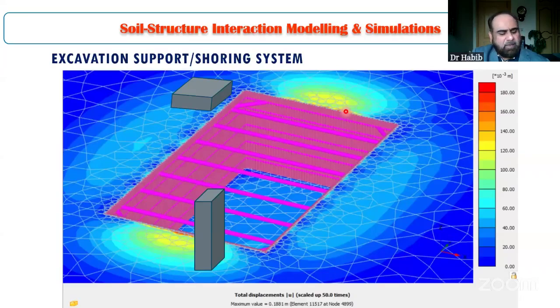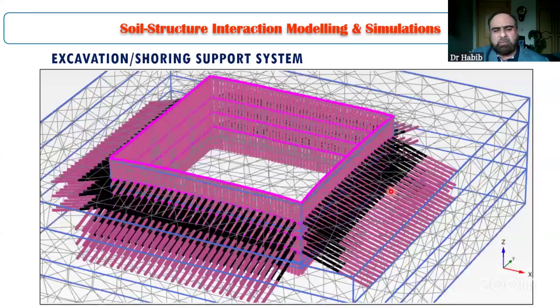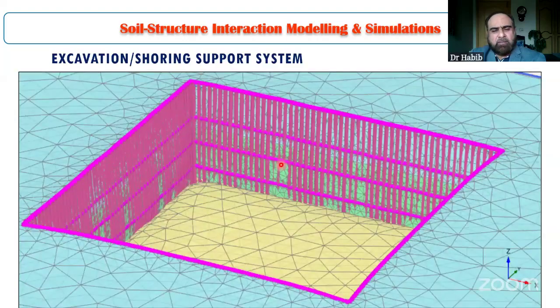But a collapse mechanism again is something which is basically subjective. And in empirical systems, for example, we calculate the integrity of the anchors independently and the rest of the structures independently. In SSI modeling, it can even highlight localized problems for you, like this is sand, and sand is flowing out of the piles if we don't provide complete closure of the gap.